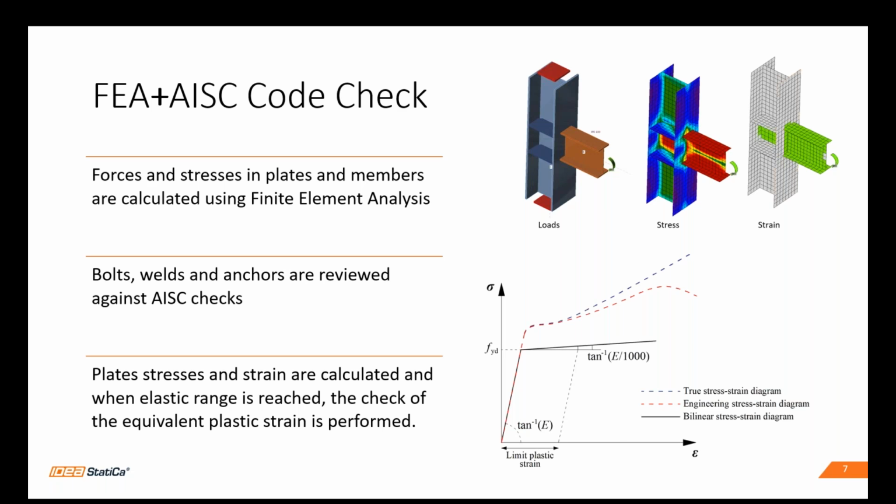Once the software has that analysis, it looks at the bolts as nonlinear springs, as well as the anchors. And the welds are broken up into finite elements as well. The nice thing is that once the analysis on these components is done, they are actually compared with AISC code equations. And that's easily viewed right within the reports and even on the screen.